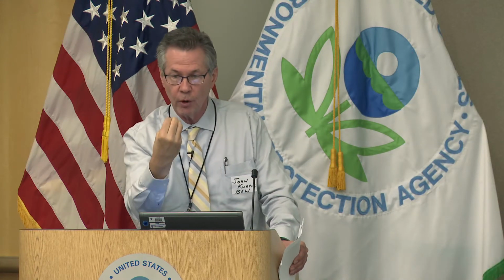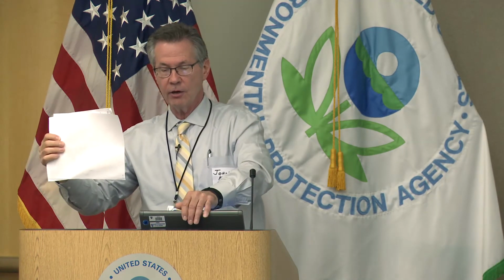It's at temperatures of about 280 to maybe 390 degrees Fahrenheit, after that heat has been absorbed for the combustion process. If I take that same precipitator, and now this is my air heater here, and I just put it over here, so it goes boiler, precipitator, air heater, other devices, then now it's seeing flue gas temperatures of 700 or 800 degrees Fahrenheit, and that's why it's called a hot side precipitator.